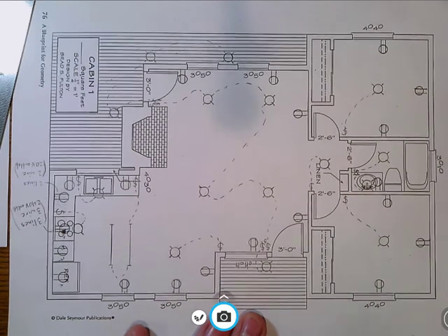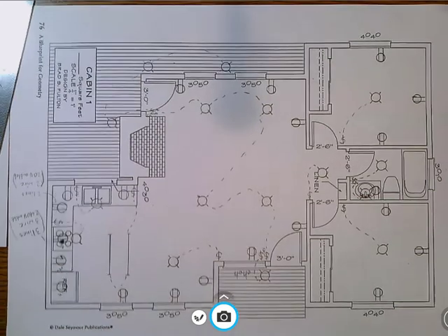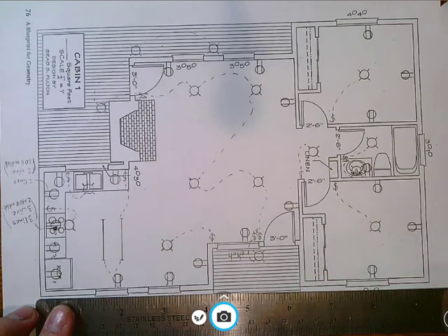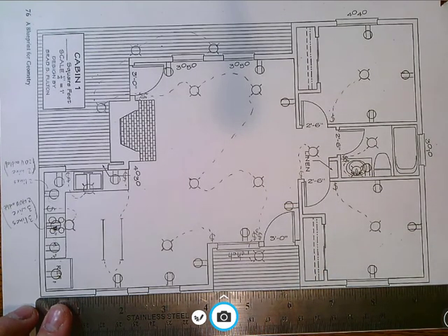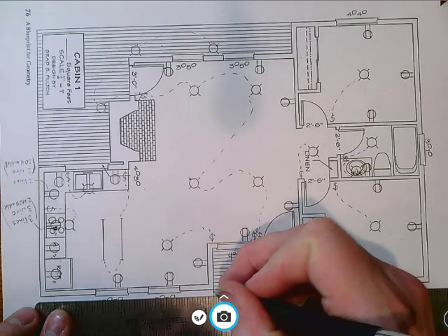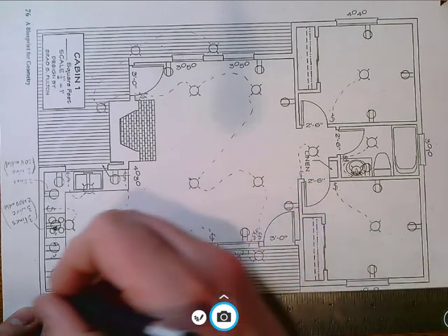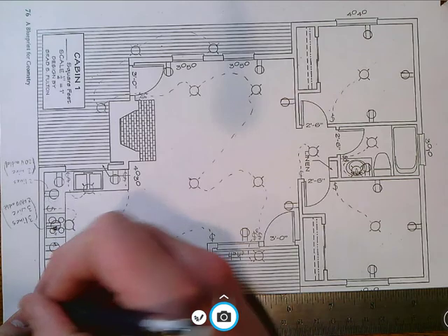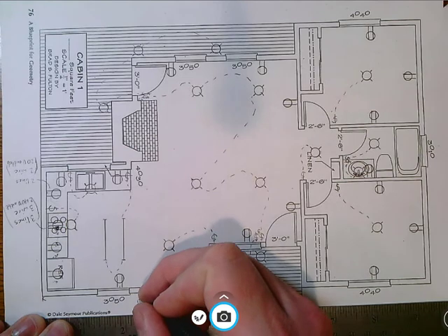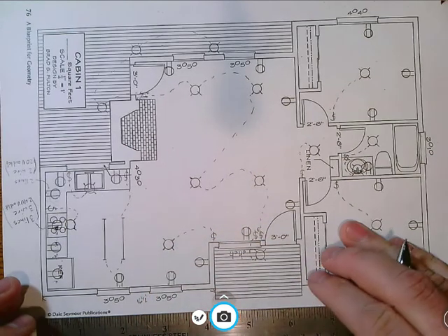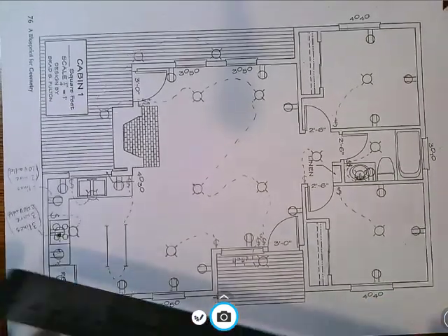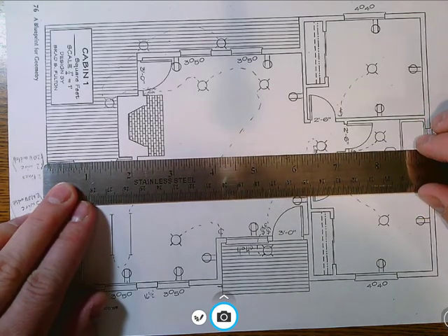If you want to see a square footage calculation again and you're just like, I want to see that one more time, hang tight and we'll do that together here. So what I'm going to do for a particular situation like this is I'm going to start splitting this up a little bit. So if you're trying to figure out what the square footage of this should be, I'm looking at here to here. And this is 4 1/8 inches. So this is 16.5 feet in terms of what the scale is, because 4 feet for every inch, the extra 1/8 inch is a half a foot. And so what I'm going to do now is I'm going to try to sketch some lines here